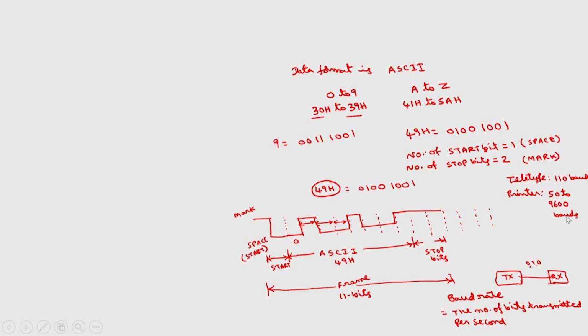Suppose I want to transmit here, the specifications I have given, in addition to this, if I give the specification as baud rate also, baud rate I want to operate at 1200 say, then what will be this gap? What will be this duration of this signal? So, what will be this duration? How to compute this? So, baud rate is defined as bits per second. Okay. 1200 baud means